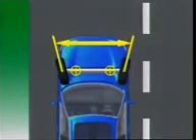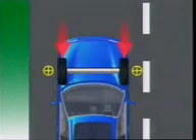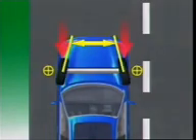The effective scrub radius, positive or negative, is to provide a turning moment which attempts to turn the wheel away from the central position when the vehicle is in motion. On a rear-wheel drive vehicle with positive scrub radius, the vehicle's forward motion and the friction between the tyre and the road causes a force which tends to move the front wheels back.